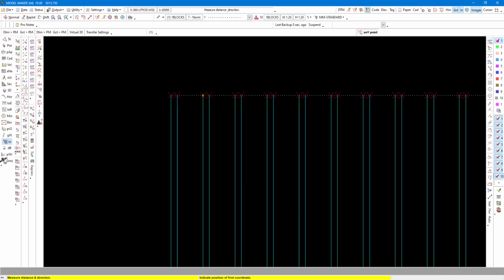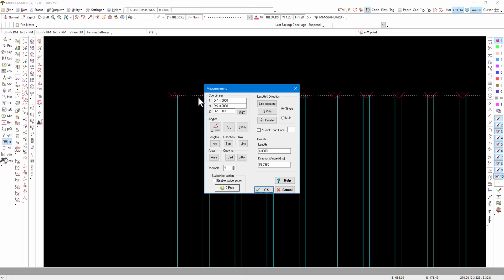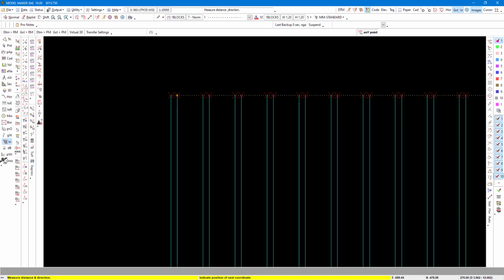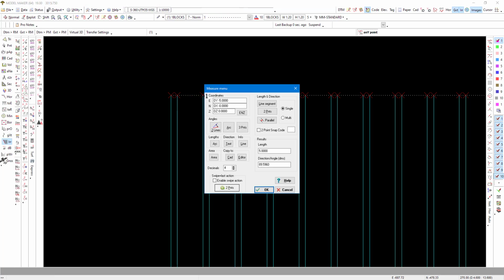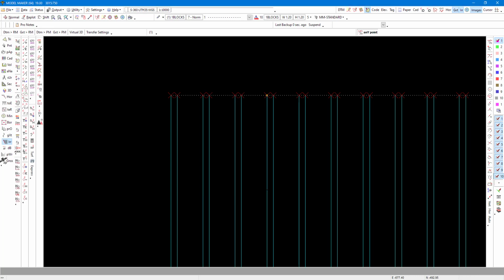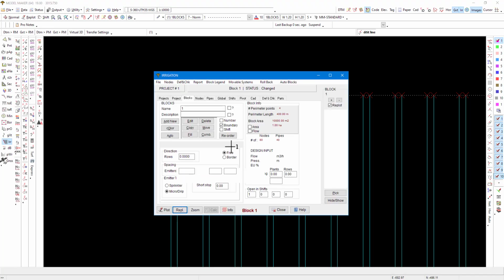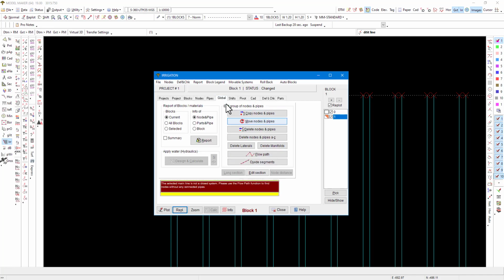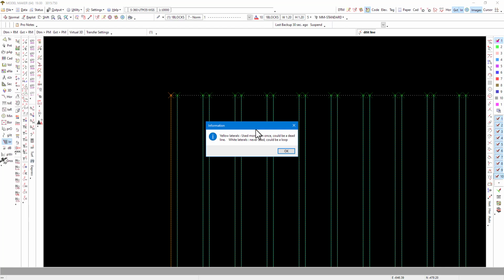And we'll measure from there to there. That's 4 meters. And the primary is actually 5 meters. So it's two totally different ways how the software does the same thing. And I prefer this method using the tramlines option, and I'll show you why. So I'll just go and delete all my lines again.